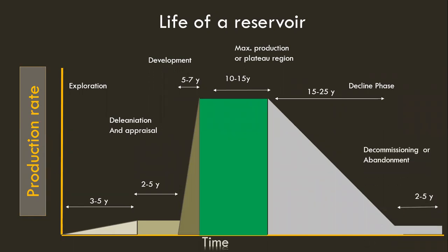Then after that, if you believe that the oil which was present inside the reservoir has been extracted to the best of the technologies we have, then we have to abandon the well. If not, if you think that we need certain maintenance operations, then we have to go for decommissioning. After that, we can abandon it. So this is the last phase. It is not just to leave the well as it is, but before that, whatever activities have to be done in the decommissioning phase as well as abandonment will be done, and it will take around 2 to 5 years of the lifespan.